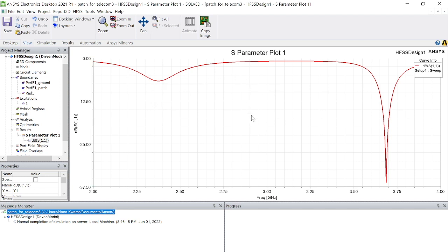And in actual sense, the reflection coefficient that corresponds with the -10 is 0.333. And when you compute the loss, you have the loss to be around -10 dB, which is fine according to theory. And we can see where our dip has shifted to. For patch, it has a lot of issues, and you can shift this dip back to 2.5 by using optimization.